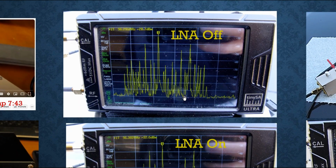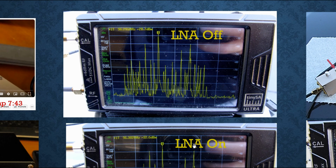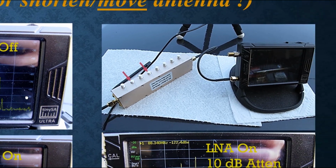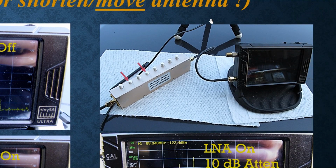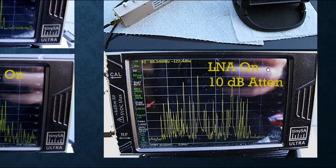Now, I can't turn the attenuator on inside this radio with the LNA on because of those 2 different signal paths that I showed you in the teardown picture. But what I can do is apply an external attenuator, and that's what I've got here. The antenna has a cable that comes into this end. I punch in the 2 and 8 dB buttons, so I've got 10 dB attenuation through this, and then that goes into the spectrum analyzer. And here's what I get.